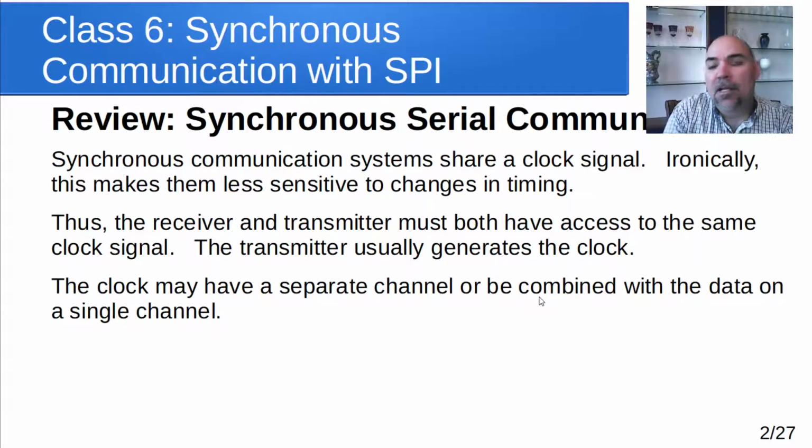So first off, back to synchronous communication. A quick review of that. The idea with synchronous communication is they have this shared clock signal. So in other words, there's a clock that ticks, tick, tick, tick, tick, up and down. And both the sender and receiver have access to that clock. They can both see that clock, and it has to be a shared clock, meaning that it's not like the times were just set the same, or they're using a crystal that has the same frequency. It's actually the same signal they're both using.